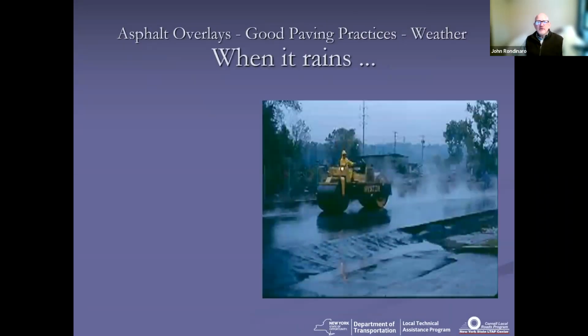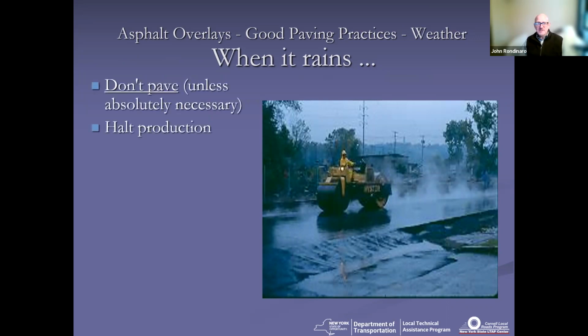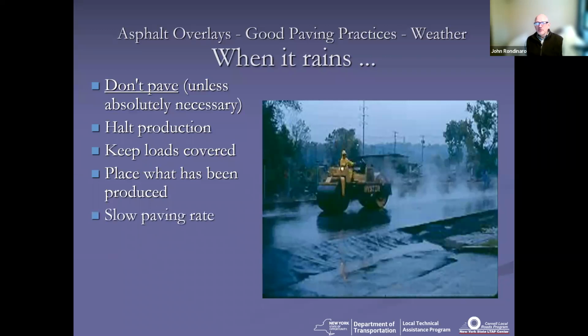And then when it rains, anybody like to pave when it rains? Just raise your hand. I hope David doesn't see any hands, because when it rains, don't pave unless absolutely necessary. No hands. Good. Halt your production, keep your loads covered, got to keep that water away from that pavement or that material. You're going to place what's been produced. You've got to get that out of the truck. You really want it to have any kind of hope in terms of compaction.